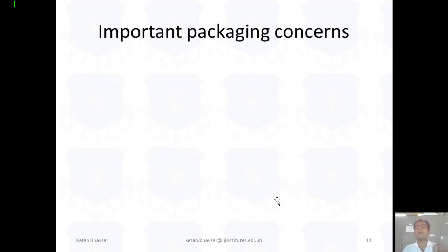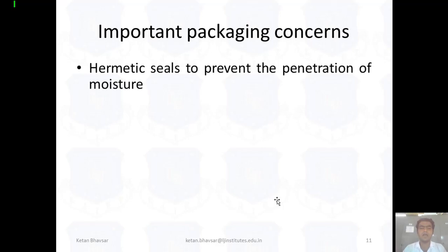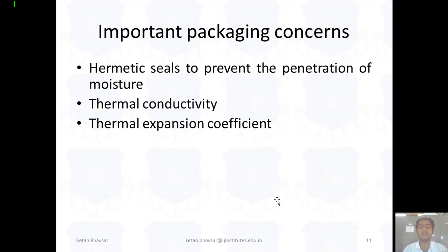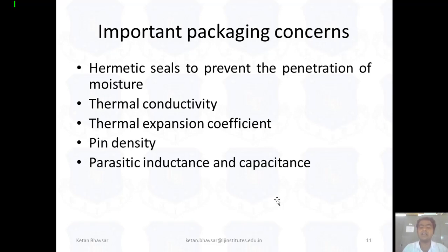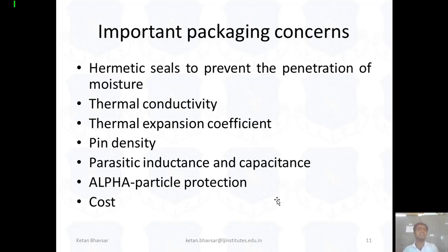Then the important packaging concerns: hermetic seals to prevent the penetration of moisture, thermal conductivity, thermal expansion coefficients, pin density, parasitic inductance and capacitance, alpha particle protection, and cost. Whenever we're talking about packaging technology, we have to take care of the moisture level, because whenever you design a product, it will be used all over the world.